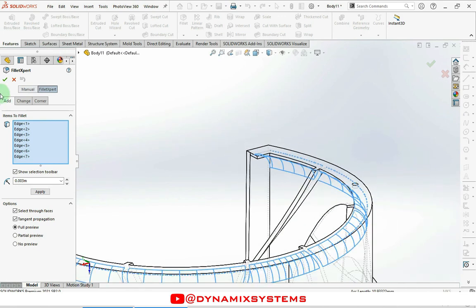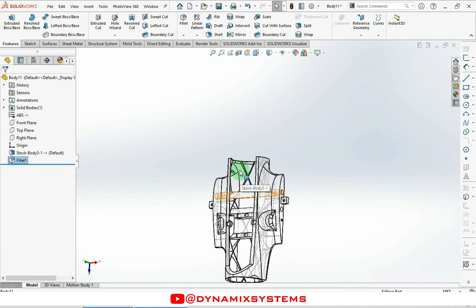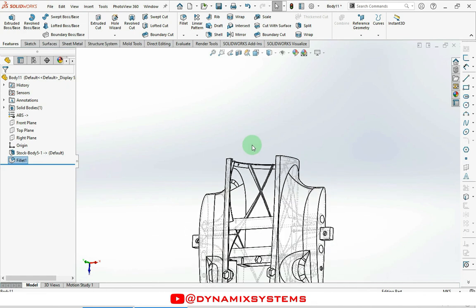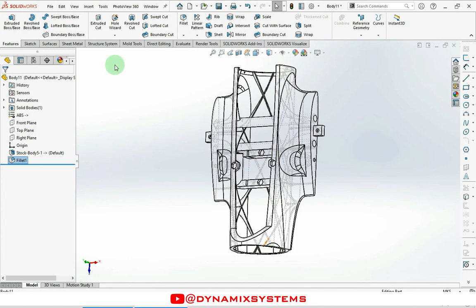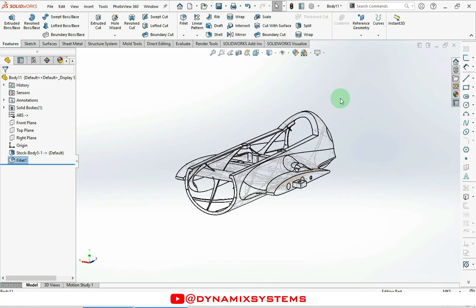I do not select it. So you just need to add these fillets on the one side, not both of them. So this file is actually ready to save it as STL file, export it to the slicer or any slicer that you use, for example Cura, and it's ready for the print process.